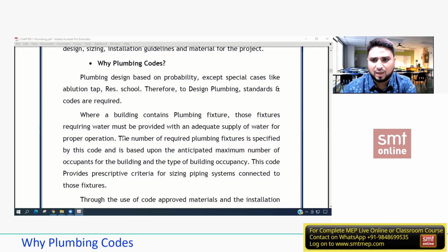Yes or no? If I have 1 inch and I'm going with 3/4, then what happens? I'm compressing. Sorry, velocity will increase, because the diameter is lesser and the Q is the same, isn't it? Yes. This compression is also not accepted, because again it is related to the pressure. For example, if only 5 psi is needed but I'm getting 10 psi because of compression, the velocity will increase, and that will damage the fixture. So in plumbing, always remember, neither undersizing nor oversizing is accepted.